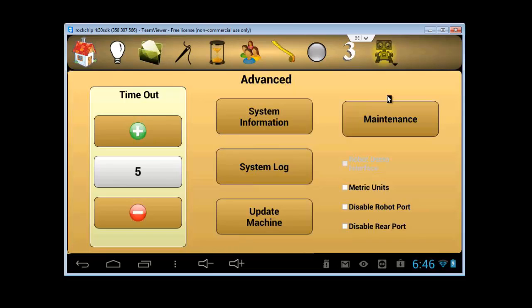I feel better about that. I didn't like that 6-month thing. Yeah, for sure. So this is a little timer that's going to let you know kind of when you need to do that. And once it hits that timer, it's going to say, oh, you really need to do your oil. And you put your oil in, and then you can hit reset on this maintenance clock, and it'll reset back to 8 hours. So that's just a little reminder that you're going to get updates letting you know when to oil the machine. Okay.